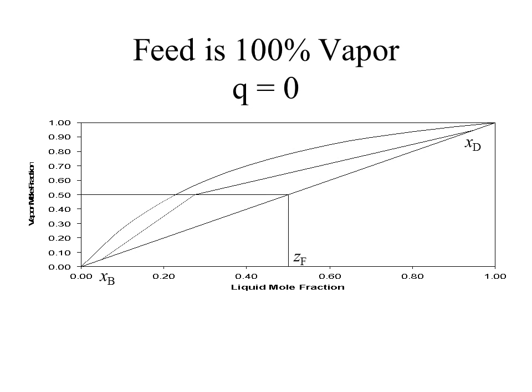Next, we will look at a design of a distillation column. We start off with our equilibrium curve, and we have our Q line from our feed curve. In this case, the feed is 100% vapor, and it has a composition Z sub F, which is 0.5 on our diagram. So we would take a vertical line at x equals Z sub F up to the y equals x curve, and then horizontally over to y equals 0.5.